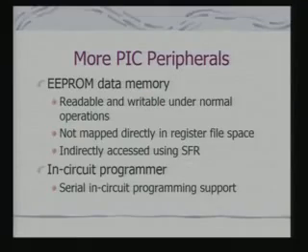Another interesting PIC peripheral is the EEPROM, the electrically erasable PROM data memory. So far we have seen data memory and discussed data memory as registers which were in the RAM area. Now, we are talking about electrically erasable memory. In fact, this provides you a facility for storing the data even when the power is out, or in some cases when you have not operated the system and you want to record the status for subsequent debugging, and so on and so forth.